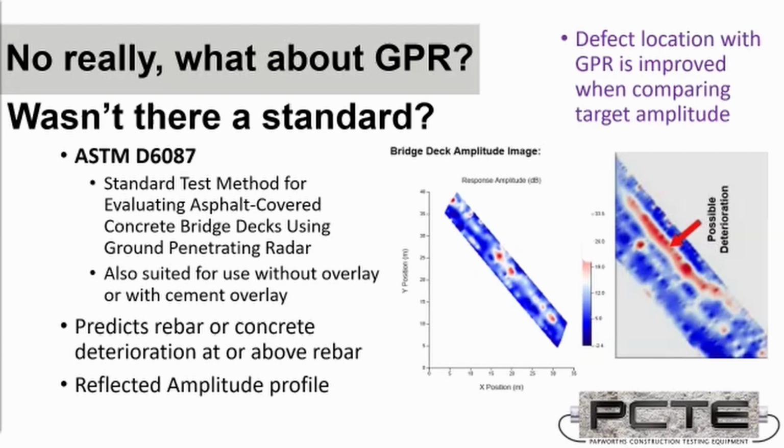This is most commonly used for bridge decks, of course, or structures which are maybe exposed to salts in America and are at risk of expansive corrosion of the reinforcing steel. And the degradation effect essentially is caused by some combination of physical damage, the presence of salt and corrosion product around the reinforcing steel affecting that signal, and differential levels of moisture around that reinforcing steel, all of which will have an effect on the signal strength of those reflections.